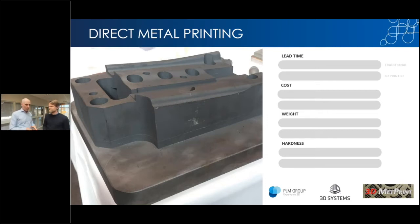And then we looked into 4 metrics: lead time for the tool, cost for the tool, weight of the tool, and also the hardness of the tool. Since it's going to be running for a long time in stamping, it needed to have a high hardness. First of all, lead time today takes about 8 days to produce one of these tools. With 3D printing, it took less than half of that. So 3 days, including all steps.